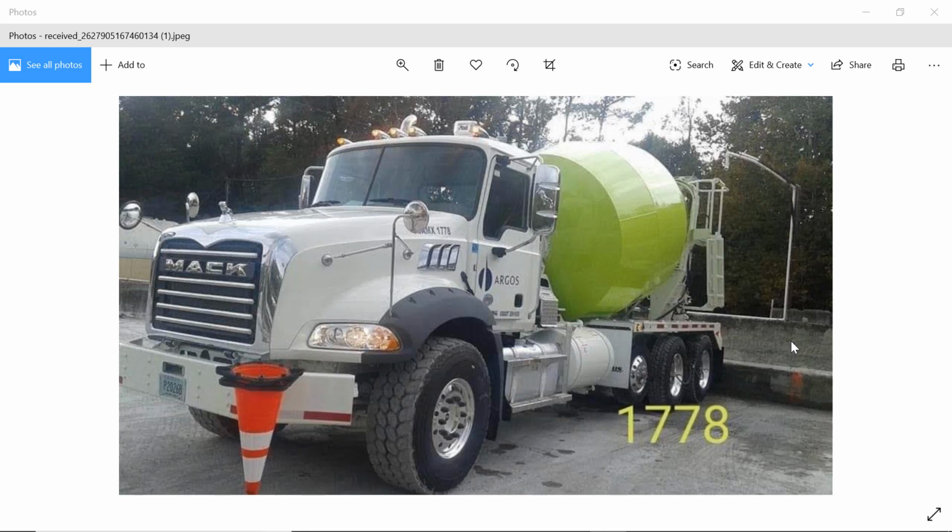1,366 times 1.0141 is equal to 1,385.2606 pounds. Determine the adjustment in pounds. 1,385.2606 minus 1,366 is equal to 19.2606 free moisture. Adjusted water quantity in pounds is equal to 267 minus 19.2606, which is equal to 247.7394. We round that off to 248 pounds.